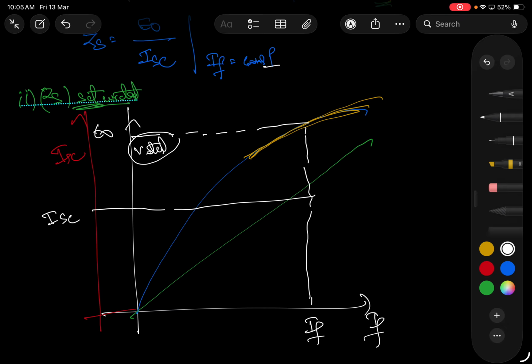I will take the rated voltage and extrapolate onto the OCC characteristics, then extrapolate onto the IF axis, and the same point extrapolated to the intersecting point to get ISC.